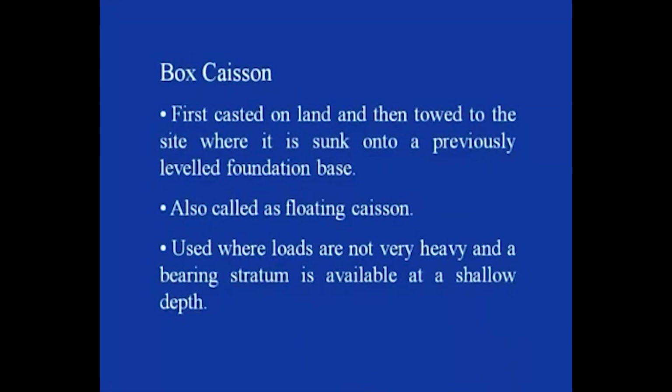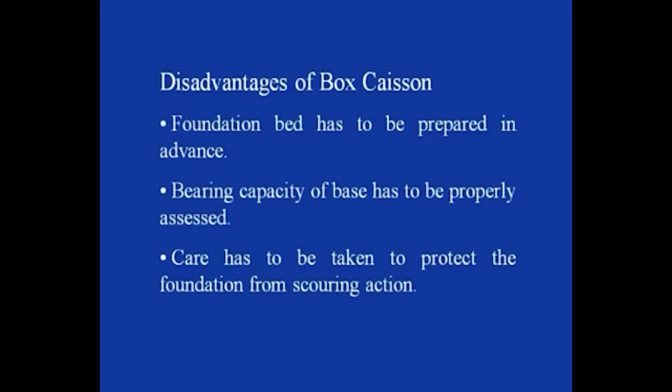where the loads are not that heavy and the bearing stratum is available at a shallow depth. There these type of wells are quite useful. Some of the disadvantages associated with such type of well, that is box caisson, is that first thing is that because it is the prerequisite that the foundation level or foundation bed has to be prepared in advance, that becomes one of the main disadvantages of such type of well.